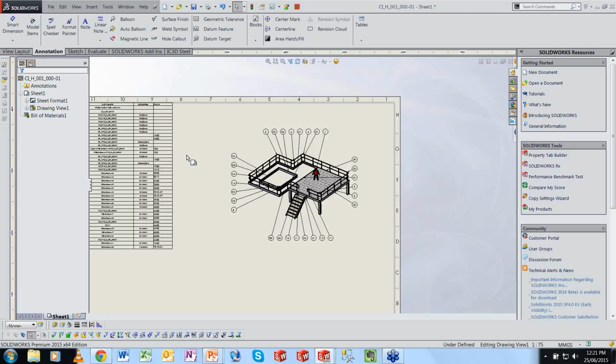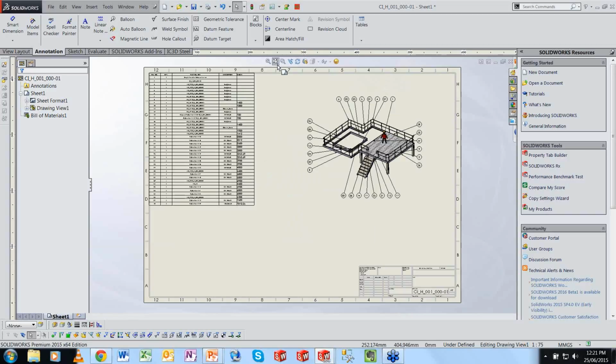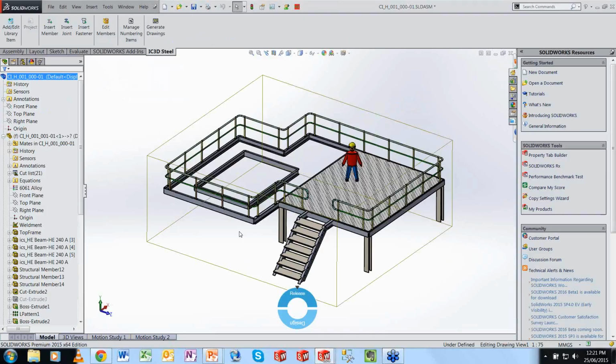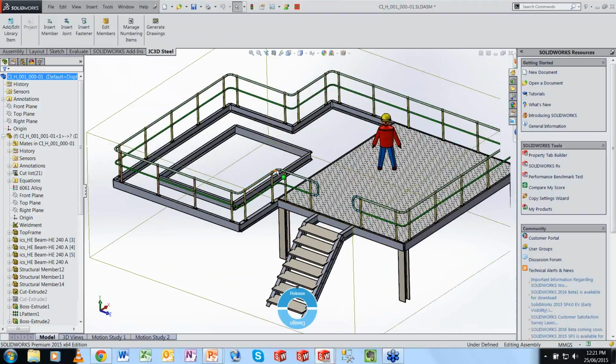So that was a little bit of what I wanted to show you, what we've got at the moment about the automated handrails module. You can see it allows for automated creation. We account for bends at corners. We account for where the handrail needs to stop because of a break or something like that. We account for the parametric nature, and it's all standard sized according to, I guess, an industry standard catalog, the WebForge catalog. So that's what the handrails module is at the moment.